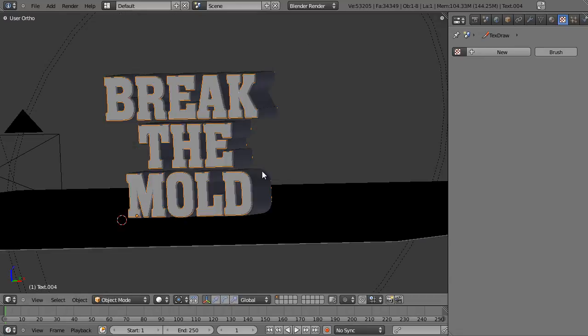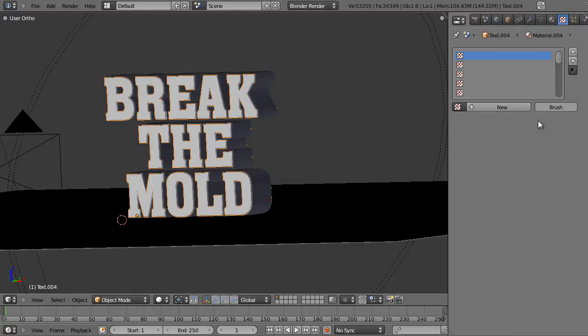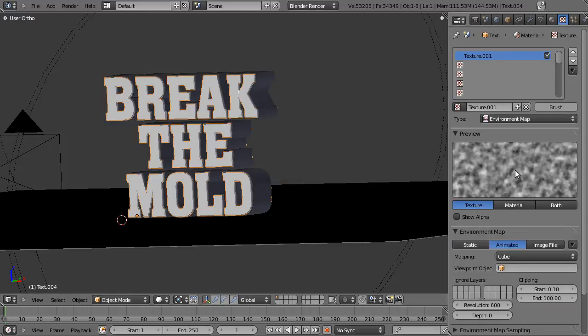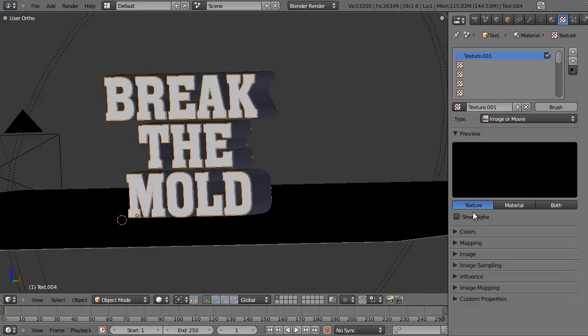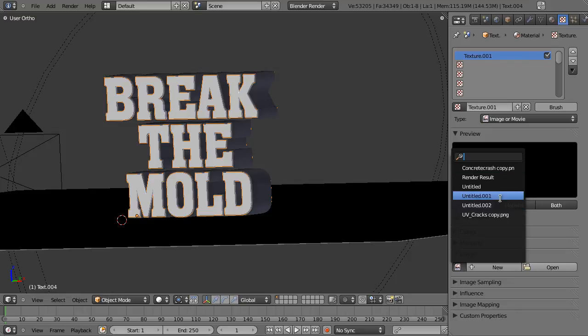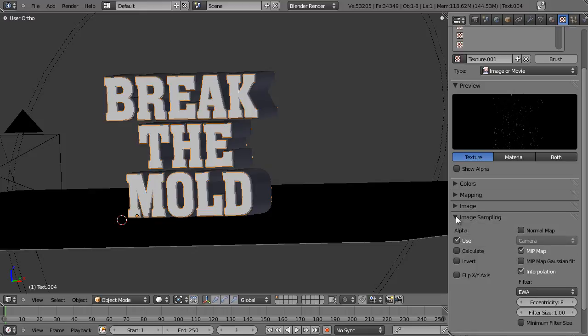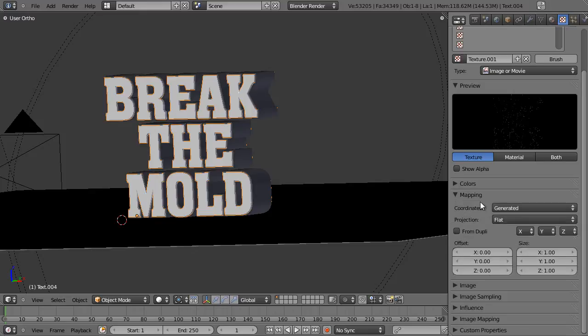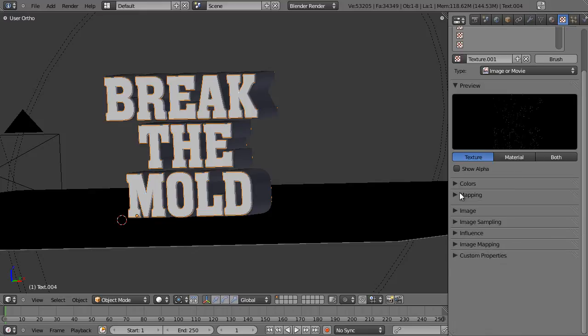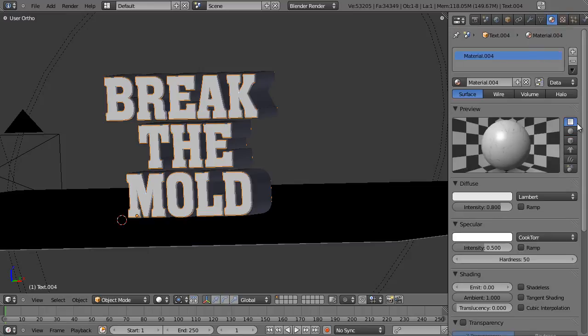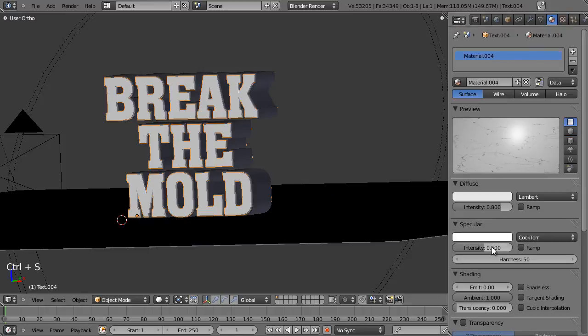So that's fine. We're going to leave that as that. We're going to give it the material now. So very basic, just add the image as you would normally. Let's go image. Select it from the list there, making sure you click pre-multiply, of course, to avoid that fuzzy look, which is very awkward. And in the mapping, select UV.